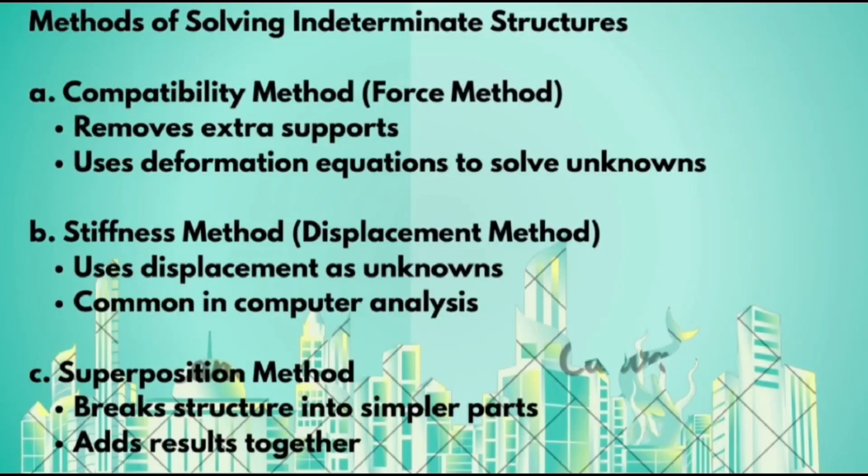Next we have methods of solving indeterminate structures. First, we have the compatibility method, also called the force method. This removes extra supports and uses deformation equations to solve unknowns. If you don't know deformation equations, this is the formula: delta equals PL over AE. P is your axial load, L is your original length, A is your area, and E is your modulus of elasticity.